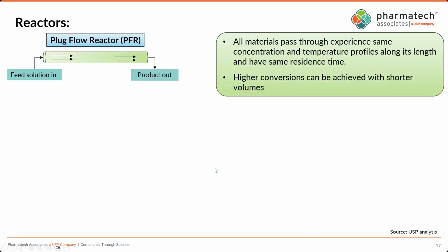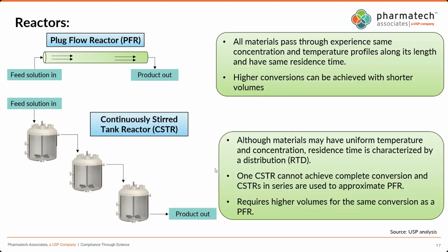The next important component in any continuous manufacturing is the reactors. Any engineer would be able to tell you there are three different types of reactors in this world: the batch reactor, the plug flow reactor, and the continuously stirred tank reactor. These are the very basic categories of reactors. Out of these three, PFRs and CSTRs are considered continuous reactors. Now we know that an ideal PFR has no axial mixing, but perfect radial mixing.